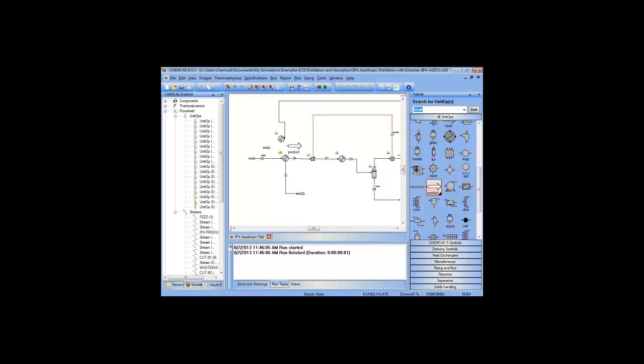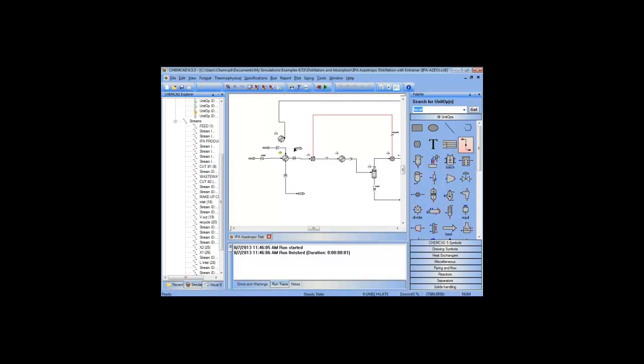And if I do something like this, this is also a good time to use a note on the flow sheet. If I'm working on this simulation, I know that this is a drawing where I have two heat exchangers because I'm trying to converge my thermal recycle. I know that in reality, this is really one heat exchanger.